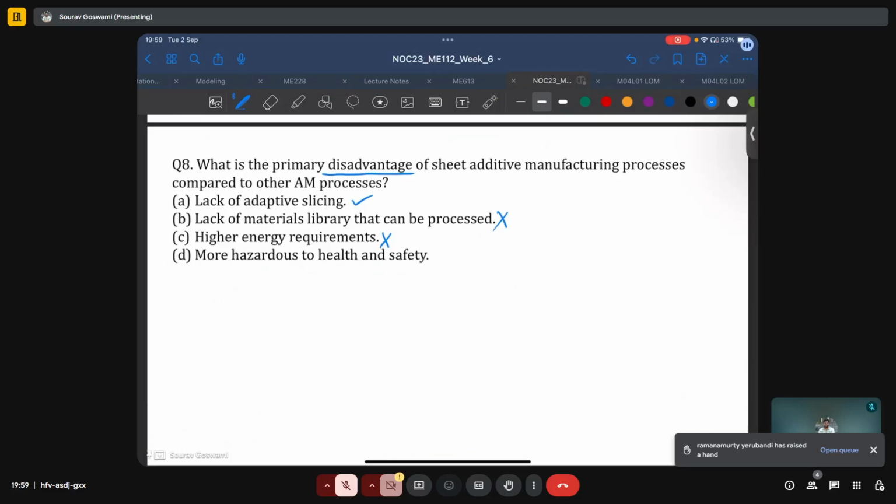Some processes might involve sintering, but even then, some of the common hazards, such as lasers, which require proper handling and laser safety, laser glasses and closed chambers, and so on, or the use of powder feedstock, which are very dangerous for human health and should not be inhaled, and thus require careful containment, cleaning, proper handling and disposal, or even liquid resins, which in some cases may be toxic to humans. None of these factors are there.